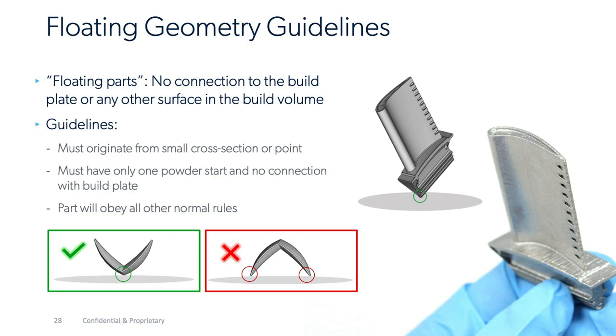You'll propagate out of those points fine, but when these two independent free-floating bodies meet each other up here at this connection, the residual stress from the process up here is going to kick these out and distort these because they have no attachment to a build plate and they're not supported. So think of it like this: if you're printing a V shape, it's fine. If you print a W, you get yourself in trouble when the two independent bodies connect.